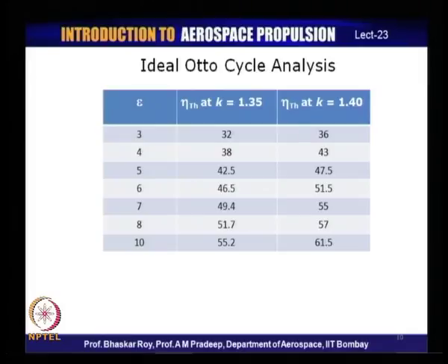So, if you use those specific heat ratios, you get various values of efficiencies, and as you can see here, as the compression ratio increases, the efficiency of the cycle and that of the engine actually increases. If you have pure air, of course, the efficiency is a little higher, but as you know, we have to burn fuel to put the energy into the system, and hence this is the kind of value that we are normally likely to encounter in actual engines.